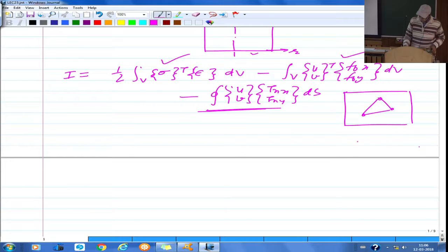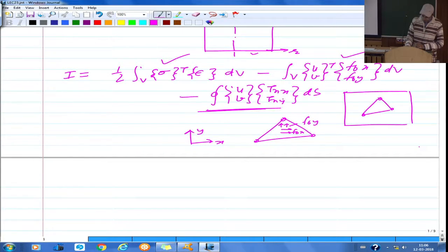So what you are doing is you are isolating this, essentially like what we did in case of 1D. You are drawing the free body diagram of this. So in the free body diagram, what you will have is of course the body forces. So here you will have in x direction, in the y direction, so this is fbx and this is your fby, see this is x and y, and then on these boundaries, this tnx, tny I said traction forces, that is force per unit area of the boundaries.